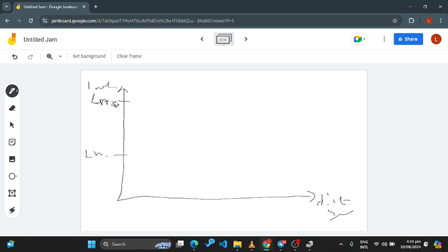Okay, so what happens is that you have this. It will drop to what? It will drop to this minimum reluctance, stay constant for a certain time, then it will rise to what? The maximum reluctance again, stay constant for a certain time, drop back to a certain minimum, that minimum reluctance again, stay constant for some time, then rise to that minimum reluctance again, in this way. This is not too difficult to draw. Is that okay?